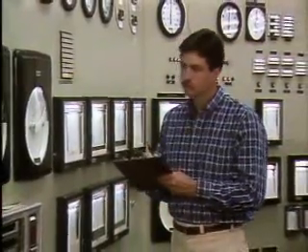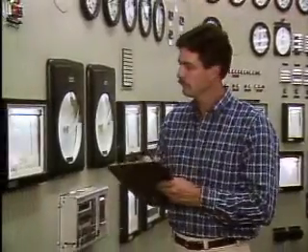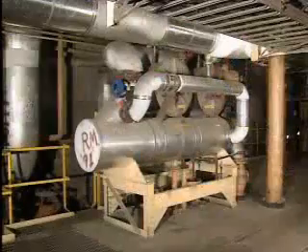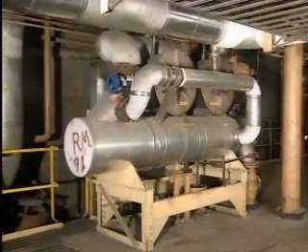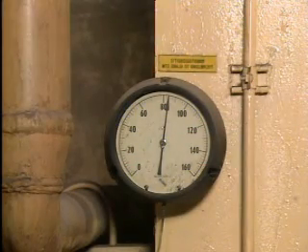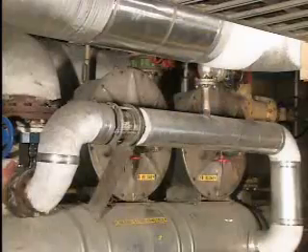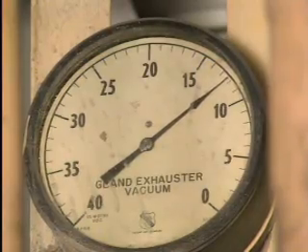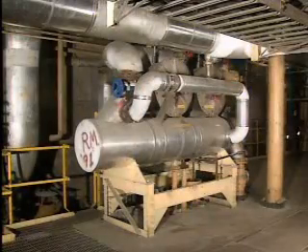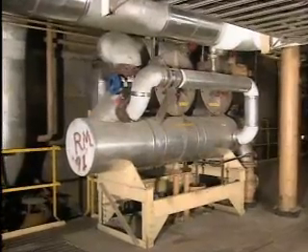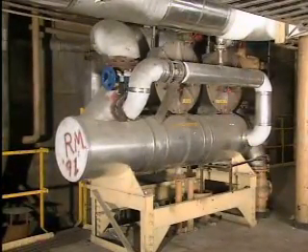The gland steam seal supply pressure should be checked to make sure that it is high enough to maintain the seals, but not so high that steam leaks from the glands. The temperature of the cooling water flowing through the gland steam condenser must also be checked. The temperature must be low enough to ensure that condensation is occurring properly. You should also make certain that the exhausters are working properly and that there's a vacuum in the condenser. And finally, check to make sure that the condensate water level in the gland steam condenser is being maintained at the proper point. There's usually an indicator that allows you to determine the condensate level.